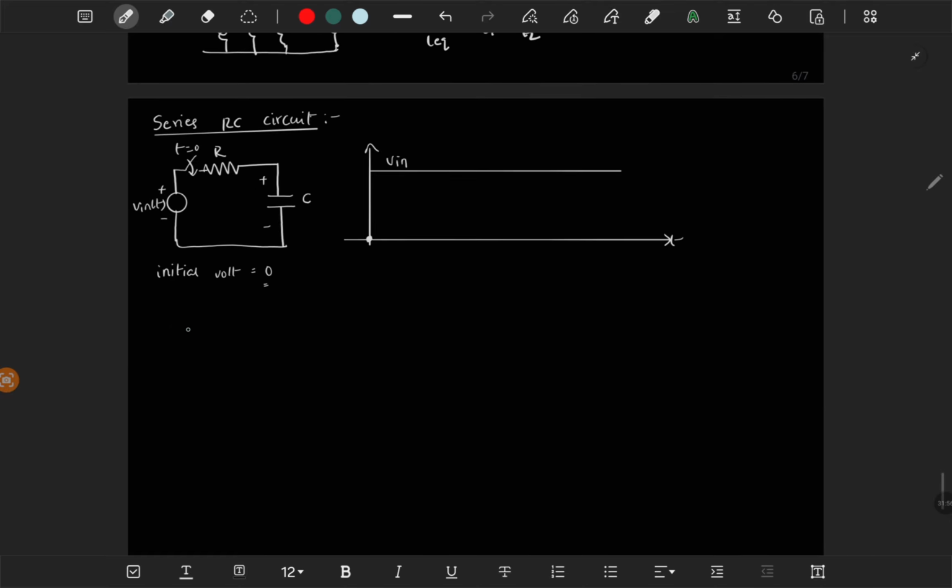In transient circuits, if you have a capacitor, then at time t is equal to 0 plus, at the time of transient, we represent this capacitance with a short circuit. Suppose at t is equal to 0 minus, we have 0 voltage across the capacitor. Then at t is equal to 0 plus also, we should have the same voltage since it does not allow the sudden change.